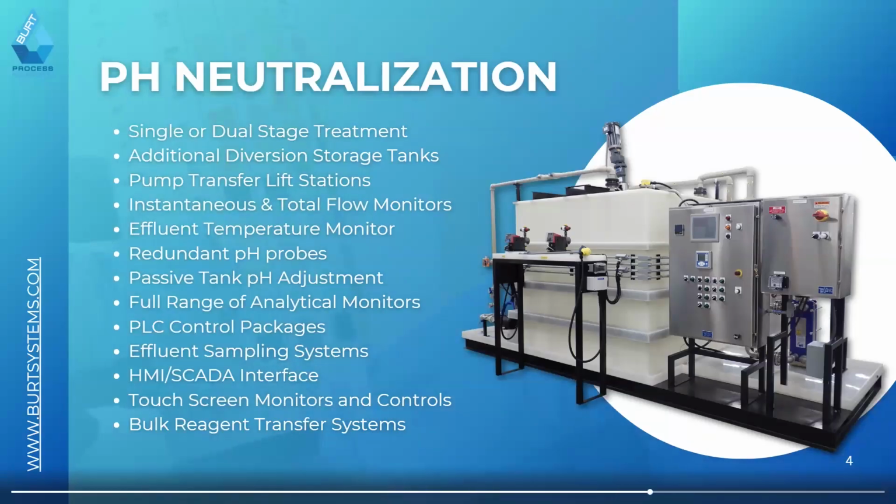If you're pushing more extreme waste streams, because pH is logarithmic by nature, 11, 12, 13 pH, obviously we're going to have orders of magnitude, so we need to look at having a multi-stage system. Because of the high flow and also the necessity for redundancy, as well as minimizing downtime as part of any pharmaceutical facility, they tend to use what's referred to as a fully automated system. So you see things like diversion tanks, equalization tanks, built-in integral batch control. We'll go through what those all mean later.